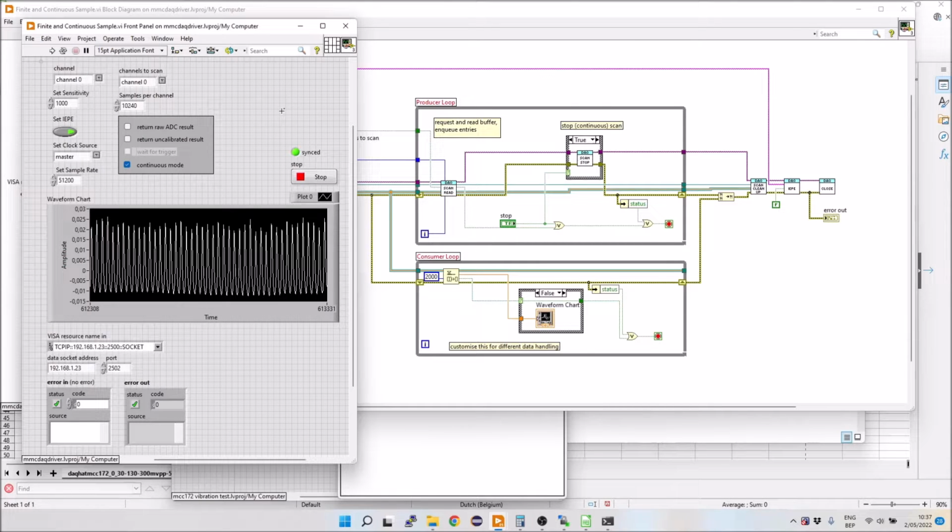Then I'm going to calculate what the average is of those values and also calculate which correction factor is needed at each of the frequency stops to see how I have to correct the input of my shaker so that the output is a linear vibration from 30 to 130 Hz.